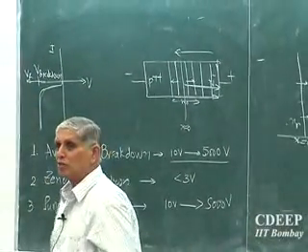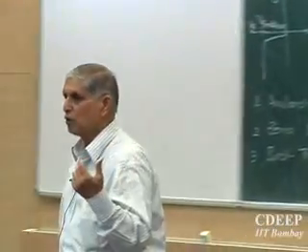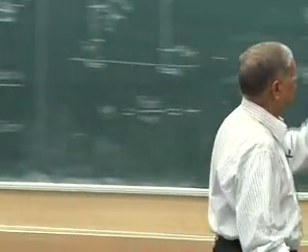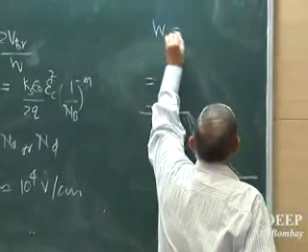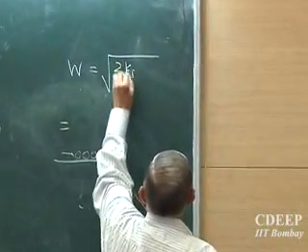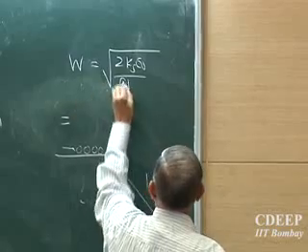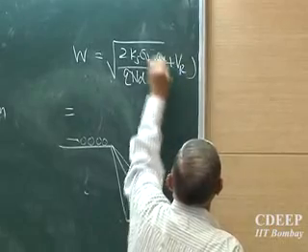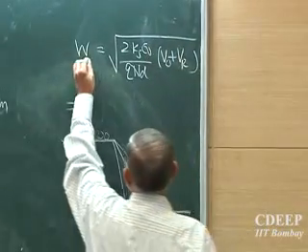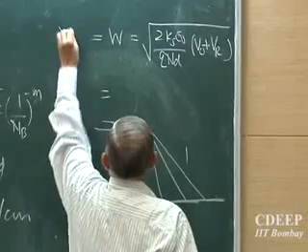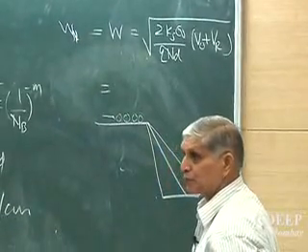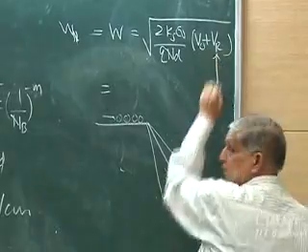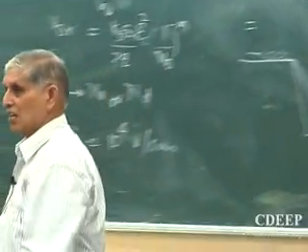Now this depends on what value then? Doping of course, but what essentially? The width of the n region you make a choice. So you can remember what is our width formula? W equals the square root of twice Ks epsilon naught, now since it is n type, over Q N_D, into the voltage. Now if this W is actually Wn, one knows at what value of VR it will punch.